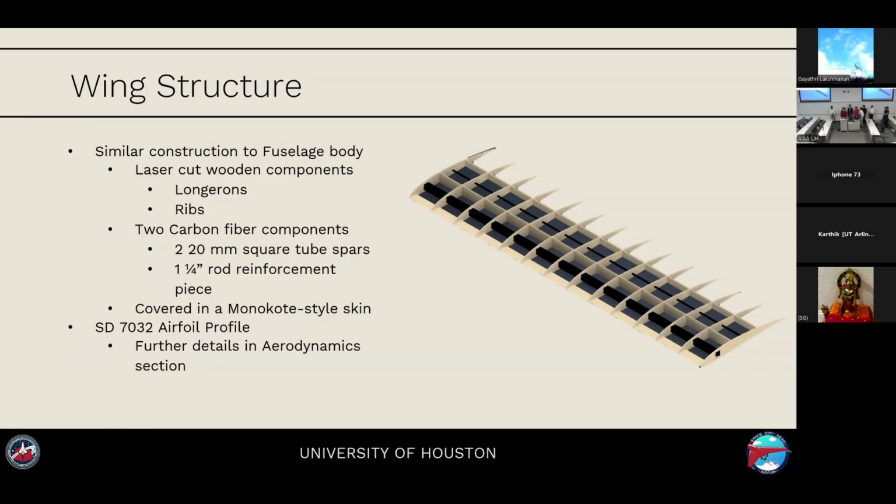Spar placement, you'll figure that out wherever the center of pressure is. But very often the balsa, or whatever wood, whether it's balsa or composite wood, those vertical strips that go along the full length of the wing are pretty good at creating a box structure. That's also good to keep twist away. So it doesn't need to be carbon to prevent twist. It just needs to have a good box structure.